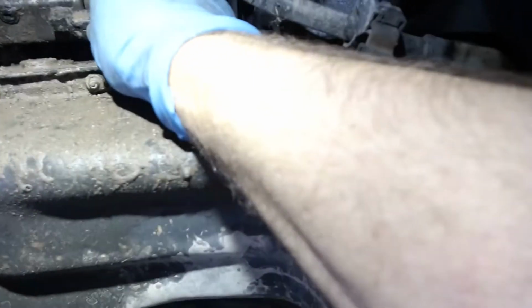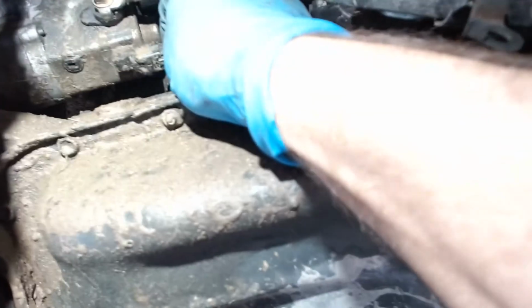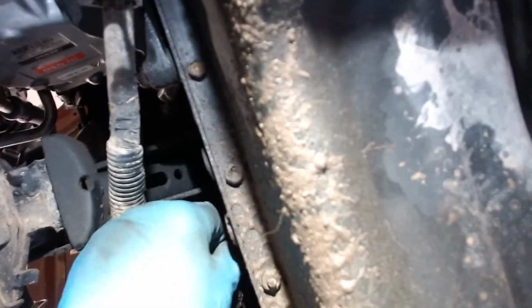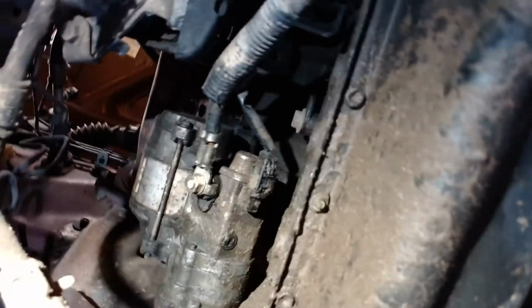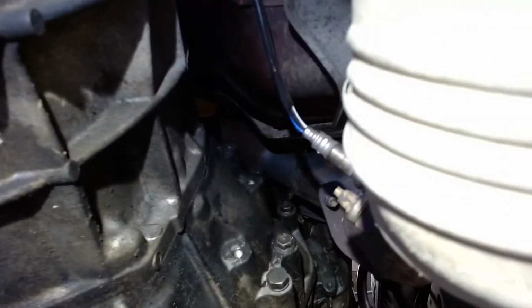So hopefully you can watch me do that. Push this little tab. I believe we're pushing that tab, but it looks like maybe it's on the top. Okay, no, I think it's there, but I'm having trouble doing it with my right hand. Let me see if I can. Okay, I can push and pull. No, I'm not getting it. I'm probably going to need to use two hands. And then the two bolts that hold the starter in are this one here and that one there. There's two 14 mils. And so we'll get those. Let me pause and I'll get that connector off.